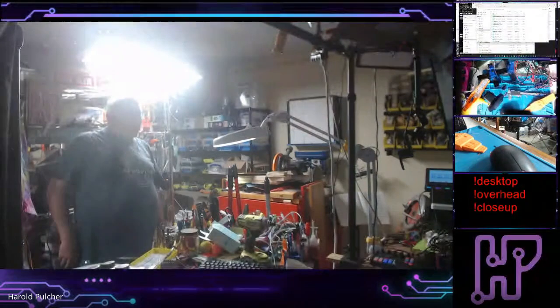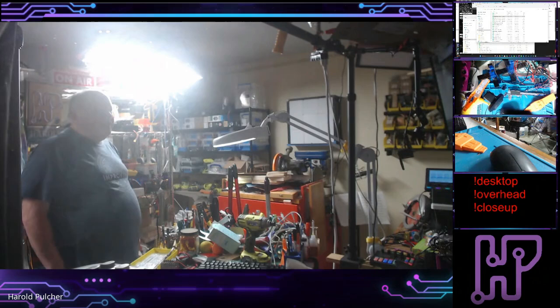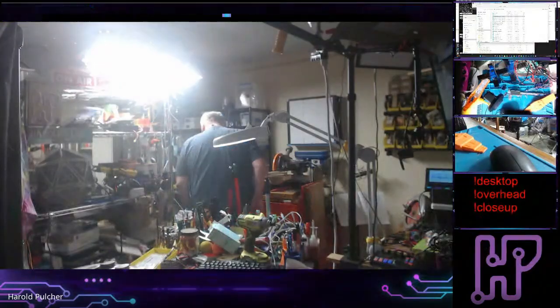Don't those work up to like 12 volts or something insanely high voltage? Who cares? I think 15. Nonetheless, it's an ideal device to hook up because it's easy to understand, and now you can look at it on the scope. You can look at the sawtooths, you can look at the RC time constant curves, you can look at the digital output, you can look at what happens when you vary the threshold voltages.